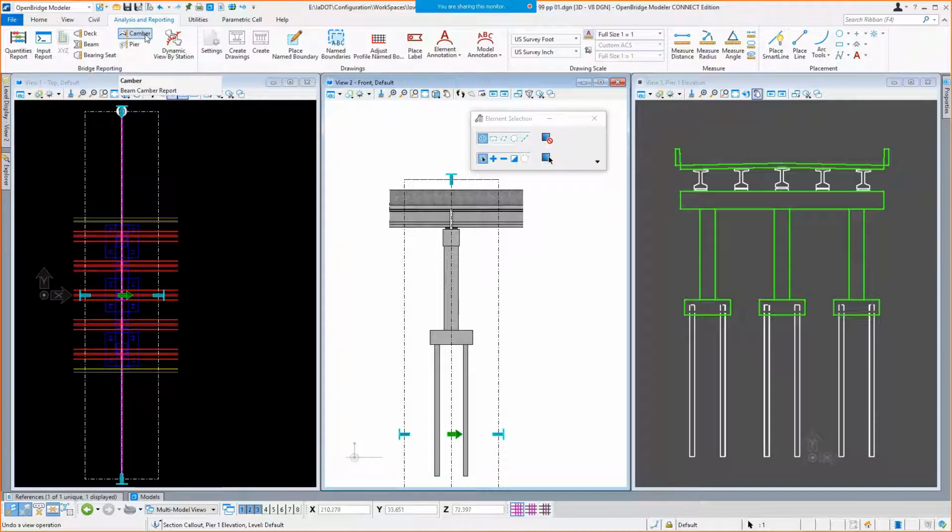And the other primary thing we can do is in the LEAP products, and the two LEAP ones specifically, if you do your footing design in LEAP Concrete or Steel, all that reinforcement that's part of that design process can also be sent from LEAP to OpenBridge and modeled as ProConcrete rebar. And it would have all that reinforcement, the same sizes, the same spacing, same everything that you had in your analytical LEAP model would be here in your OpenBridge model as well.